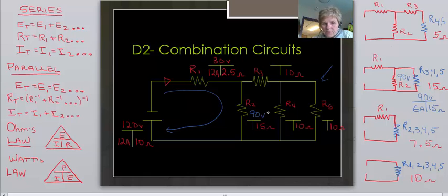The next thing we can do is say, if I have 6 amps flowing out to R345, that means I must have 6 amps flowing through R3. So I'm going to have 6 amps right there to use. And now I have two numbers. 6 amps times 10 will give me 60 volts. I can check with another closed loop. I can use the loop inside here.